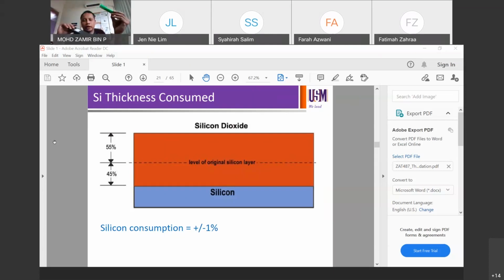On the other hand, what we're learning now is called oxidation, where to be able to get this 10 nanometers, you actually need to get some of the oxide from the original silicon. So in deposition, we introduce a completely new 10 nanometers, a new layer, onto your silicon wafer. But thermal oxidation consumes your silicon to be able to produce your SiO2. Deposition doesn't consume it, it just adds a layer, adds a coating on the silicon.